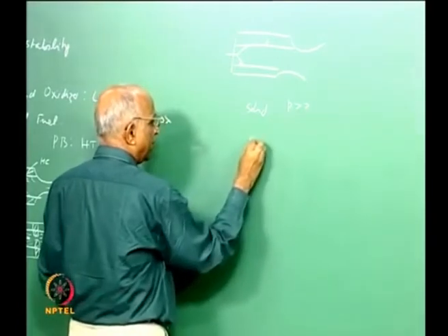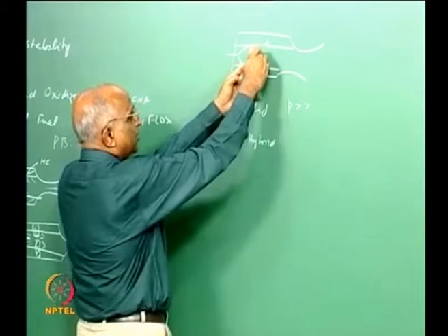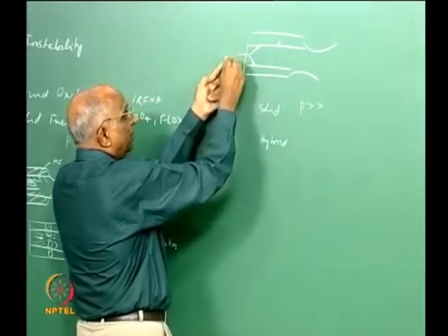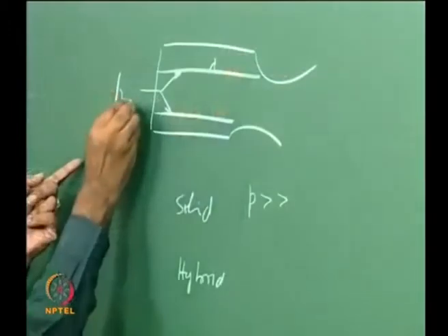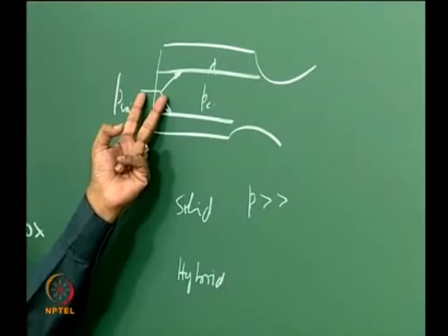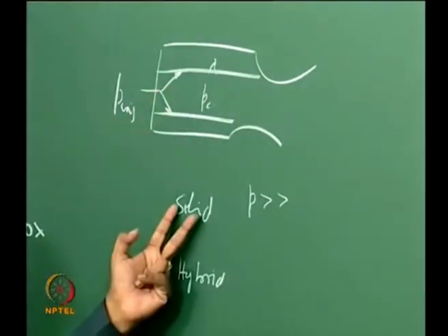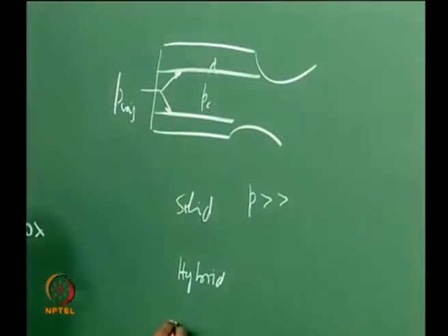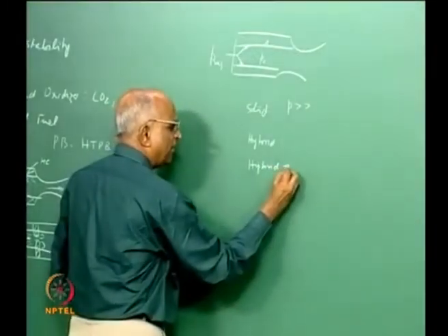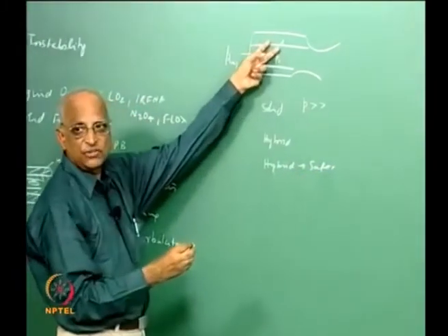In the case of hybrid, if there is some surface defect, pressure gets generated. Once pressure gets generated, automatically the pressure difference between the pressure at injection and the pressure in the combustion chamber increases, and therefore the flow rate decreases. If flow rate decreases, automatically the thrust decreases, and therefore I would say that the hybrid rocket is a little safer, and it can take certain surface defects.